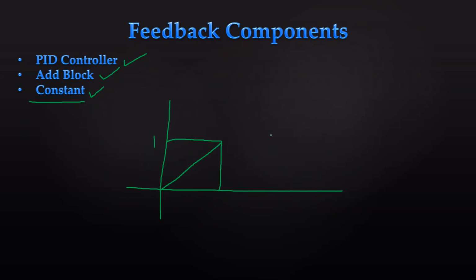So this is the basics of the PID controller. According to the input that we give to the PID controller, it will tune itself. It will give the output in the range of 0 to 1. So if we are using this in DC to DC converters, indirectly we are changing the duty cycle. Our duty cycle will also range from 0 to 1 only.